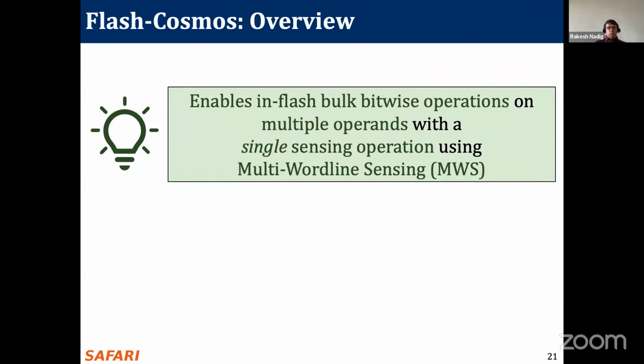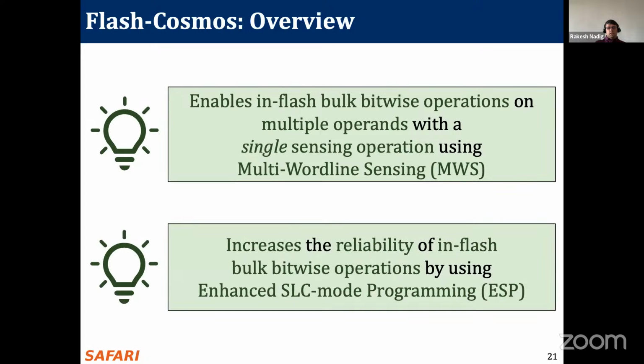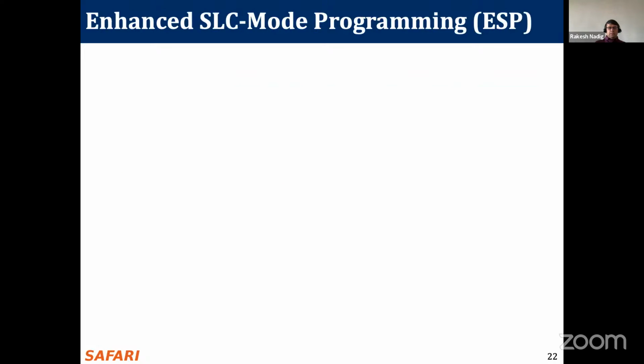So this is a brief overview of how we can perform bulk bitwise operations on multiple operands using a single sensing operation. And now we look at how we can increase the reliability of these in-flash bulk bitwise operations. We propose a technique called enhanced SLC mode programming. So let's look at enhanced SLC mode programming now.